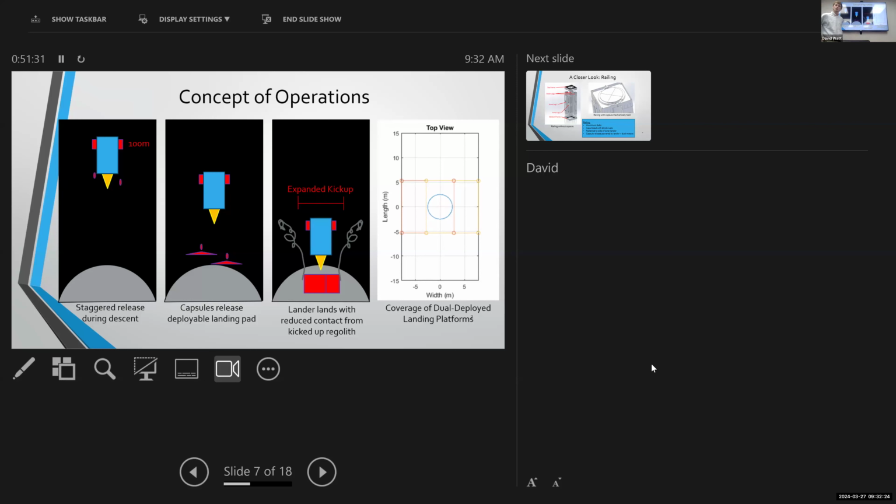So since you brought that up, that triggered a thought. As you're landing, are you anticipating New Glenn is going to come straight down? Yes and no. This lander separates from New Glenn, the rocket. Then the lander, we went into some old reports and figured out the reason why we chose 100 meters is because, based off previous NASA missions, once they had their topographic map, they weren't perfectly vertical, but the horizontal velocity was at its lowest by the time you were about 100 meters off the surface.